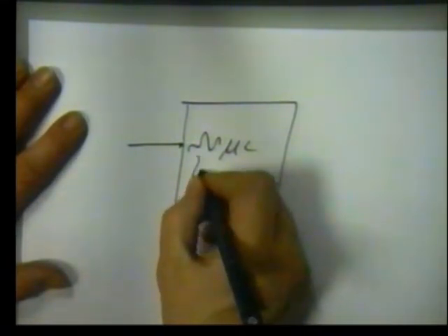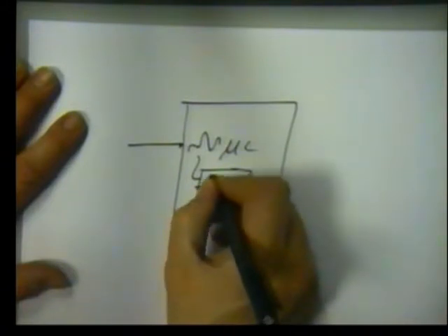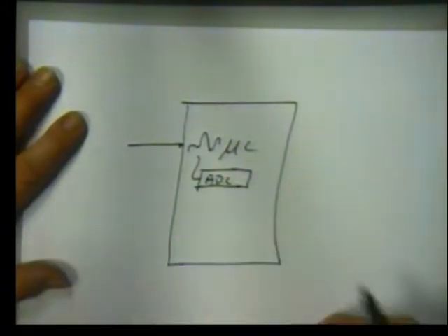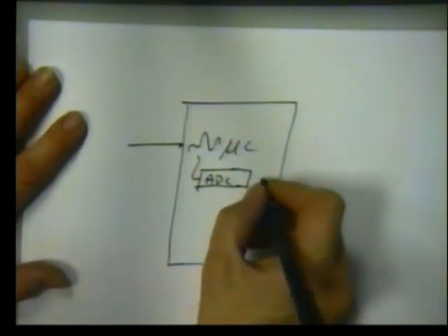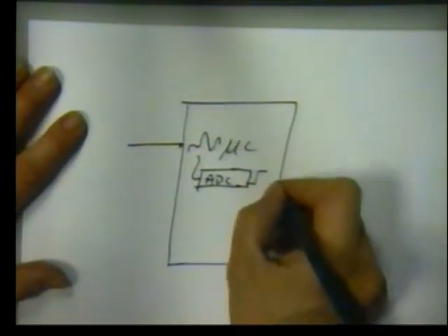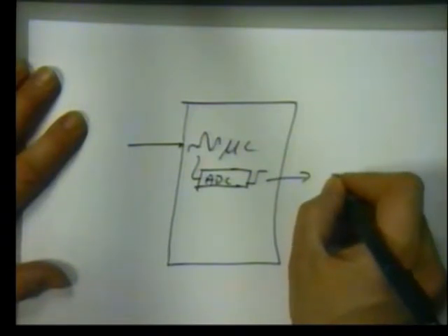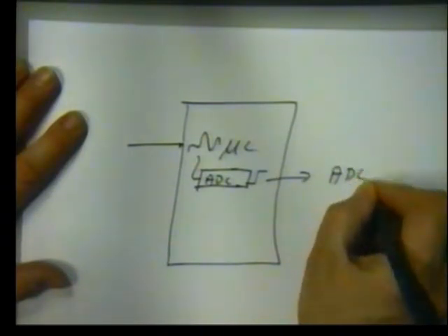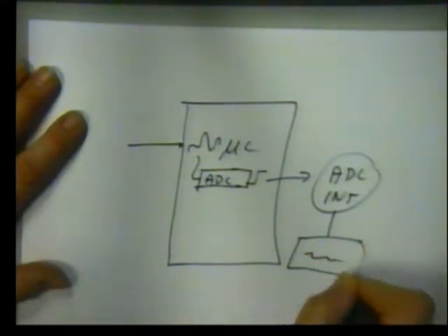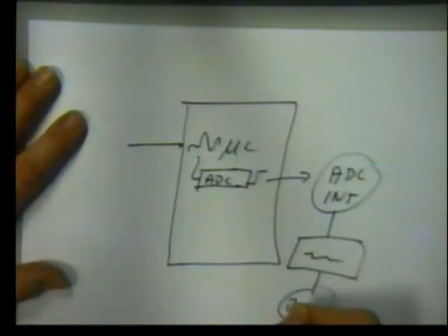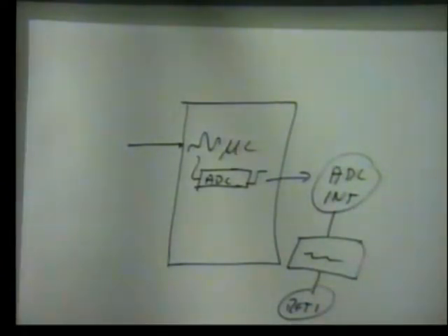And that signal goes into an internal ADC. It's actually in the chip. It's been integrated in the chip. And when the end of conversion occurs, that issues automatically an ADC interrupt, and then we can service that interrupt and then return from the interrupt internally. So it's all done for us.